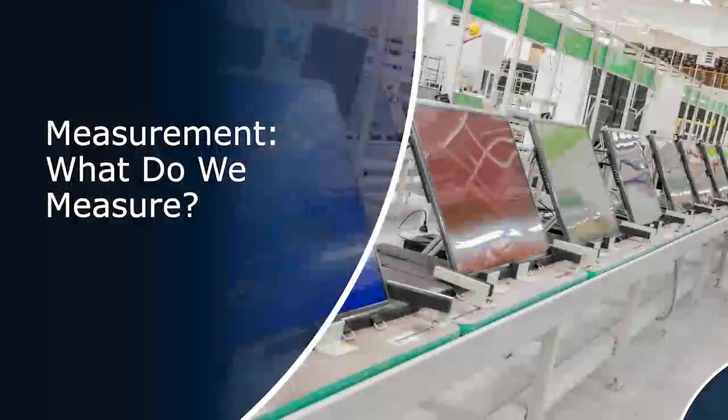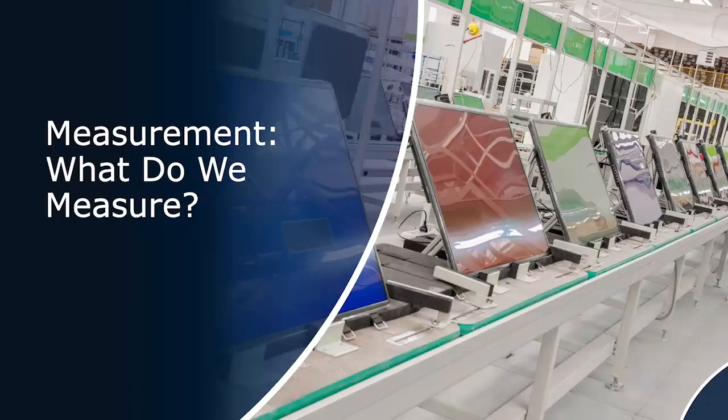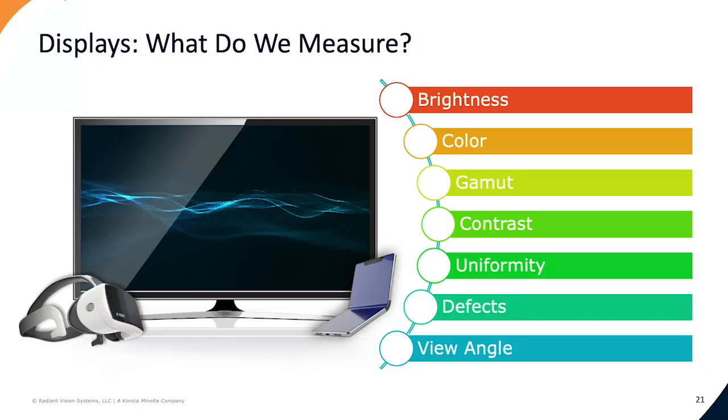Next, we will talk about some different properties or characteristics of displays that are often measured to evaluate display quality. I've already talked a lot about luminance or brightness and color. These values can also help us determine: Is the display bright enough? Is it producing the right color? Does it meet gamut specifications, such as the whole range of colors that the display can produce? What's the contrast ratio? How uniform are brightness and color across the display?